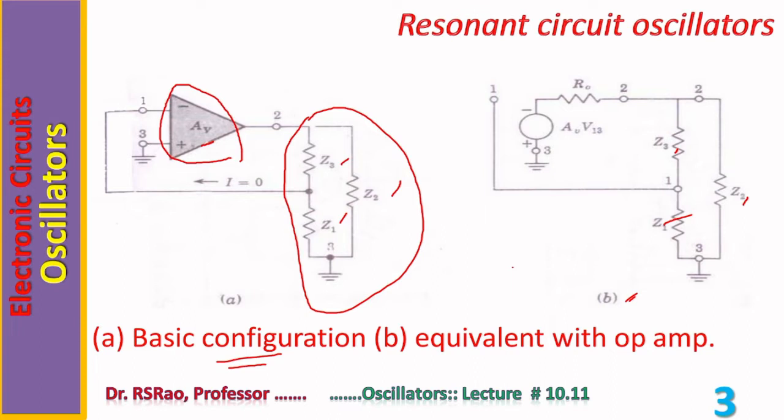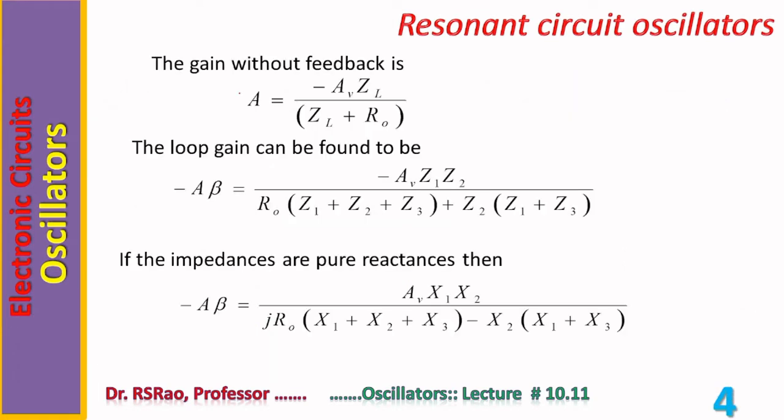Notice the design of oscillator circuits. It is based on a condition, that is, the loop gain angle is equal to 2 pi. Out of this 2 pi, pi, that is 180 degrees, is provided by the basic amplifier, and another pi is provided by the feedback circuit. That's why notice the inverting terminal is being used to connect the output of the feedback network to the amplifier.